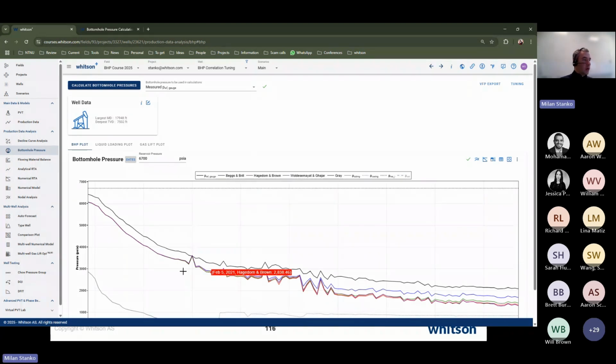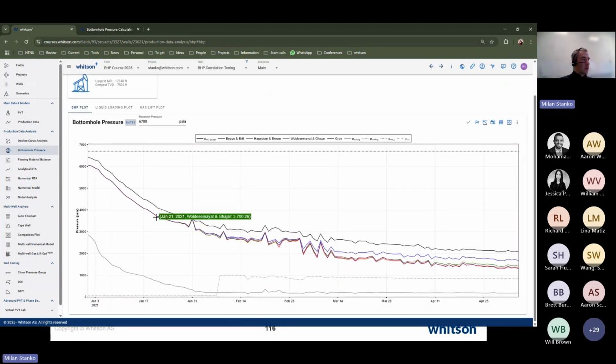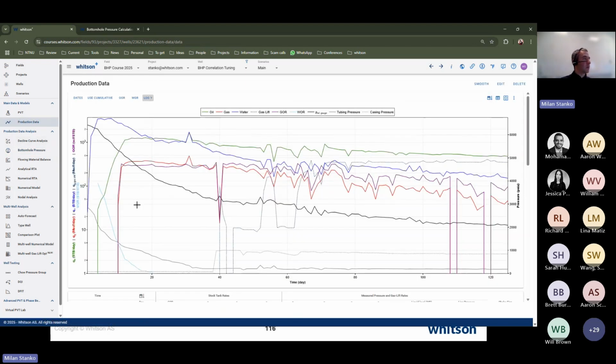Okay, so first we're going to do two things. Here is single phase flow, so we know that there is no effect from the correlation. Simply, it may be that the fluid properties we are using, density and viscosity, could be different there. And so one thing we can change, since there is water being produced on that well, is the water. The salinity of the water we are using affects the density a little bit, especially if it's very high.